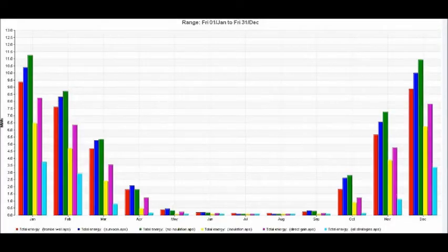The following two graphs best illustrate the drop in energy consumption and load when each strategy was tested individually and when all are tested together, starting from the most efficient to the least efficient in terms of the reduction in the total energy. When we improved the insulation, we got a 48% reduction, which are the yellow bars.